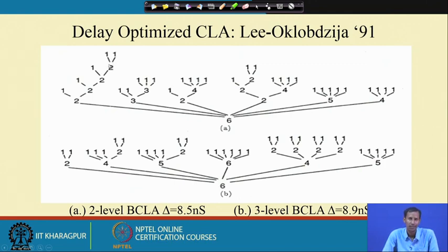This takes 2 inputs, then 1 and 1 coming over here, then 1 1 2, then 1 1 1, that means this is the 3 input, and then 1 1, then again 3. Finally, we have 6 at this particular point. So, the maximum fan in is 6 over here.